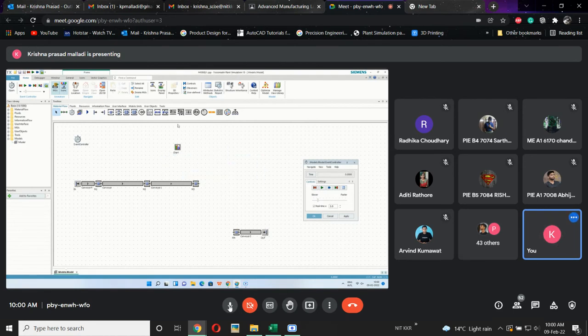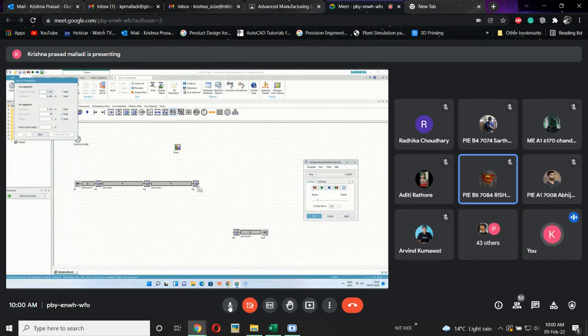For curvature, you need to click on the conveyor. So what is the first point here? M3. So we need to click on M3. After that, if you drag like this, then you will have a straight line only. You won't have any curve. But if you want a curve, then you need to press and hold control. Then a curvature will be present.